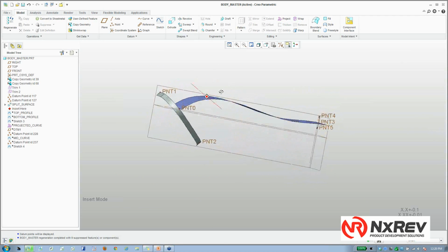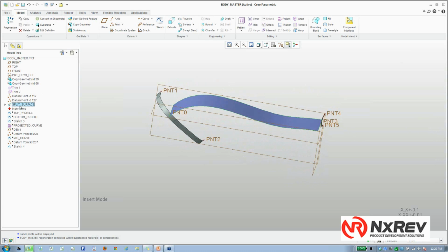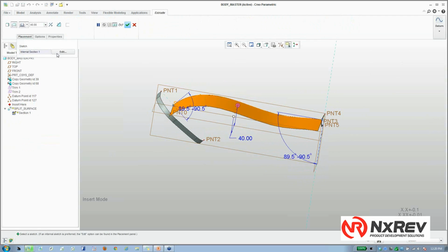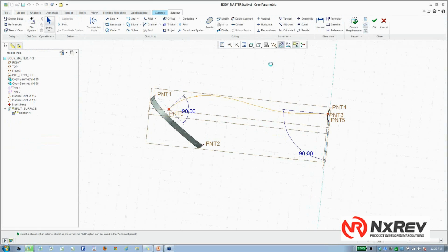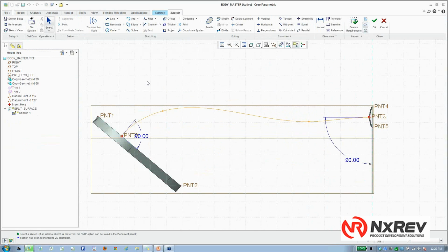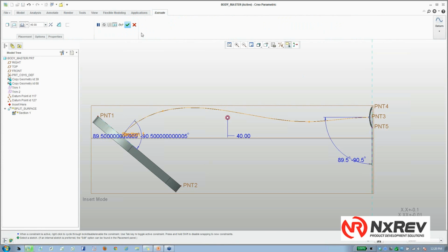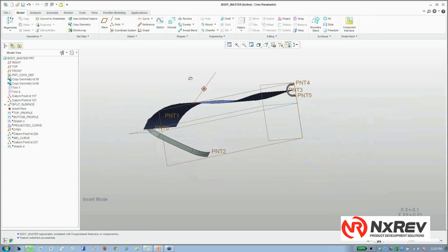Now this surface here is going to ultimately be used to project a curve onto. Let's take a look at this one. So this one was created using a spline. If you're not familiar with the spline tool, it's here, right? I'm just going to come in and start placing points, connecting the dots. Something like that. I'm not going to leave that in there, but that's kind of how this one was created. Simple as that. Had 1, 2, 3, 4 points, and I can change where those points are located to change the look and feel of the surface that I'm creating.